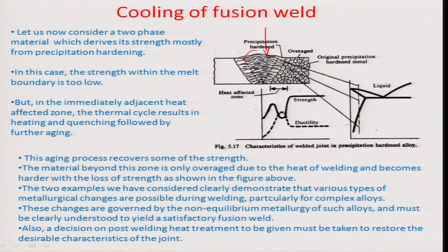In this case, a two phase material, a two phase solid solution is being solidified as the weldment, and you can think of that there is a precipitation of the grain, and this grain would otherwise go to the heat affected zone, and also may get diffused into the overall parent sheets which are being welded, and because of the effect of precipitation and the grain being inserted as an impediment to the dislocation process, there may be a strengthening action which may happen because of this precipitation followed by aging processes, okay, which takes place.